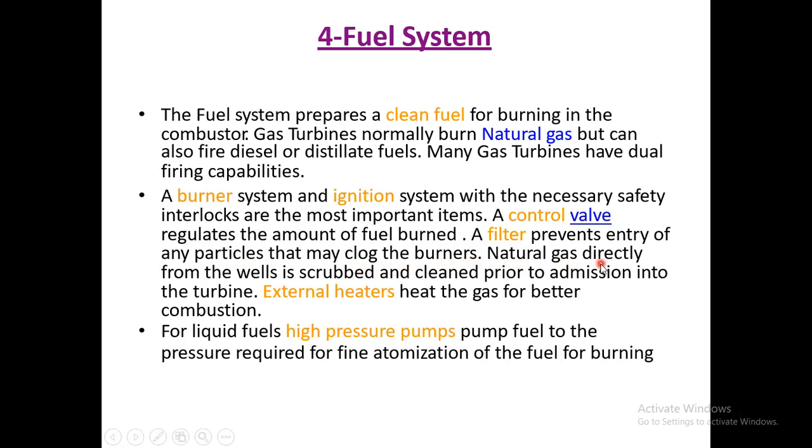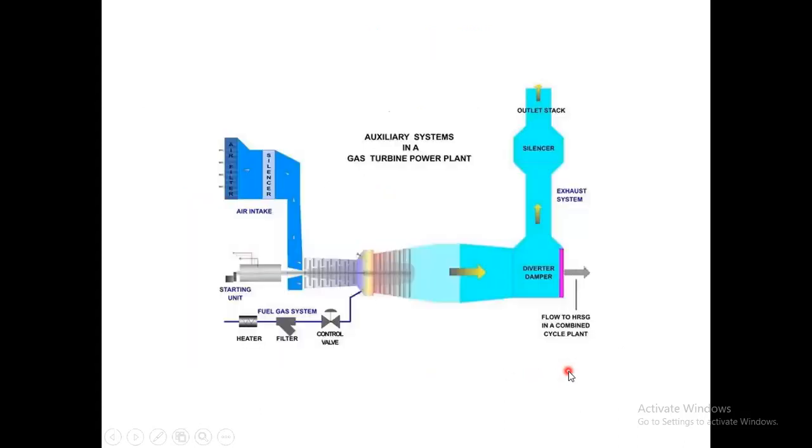Natural gas directly from the wells is scrubbed and cleaned prior to admission into the turbine burner. External heaters heat the gas for better combustion. For liquid fuels, high pressure pumps pump fuel to the pressure required for fine atomization of the fuel for burning.